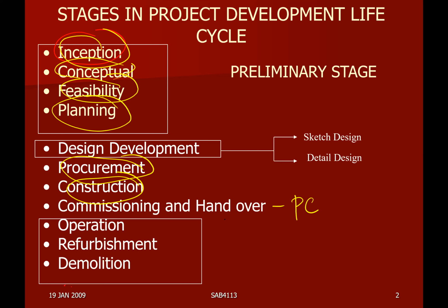But before the end of the life of the project, the building might basically get very old. So before we can even demolish those things, we can do what we call refurbishment. Refurbishment involves repair work. Okay, then after you repair, the building can withstand for a few more years. Then perhaps after that, it will go into another cycle where it's getting too old, where the cost of repair might not be a good choice. So you might opt for demolition.